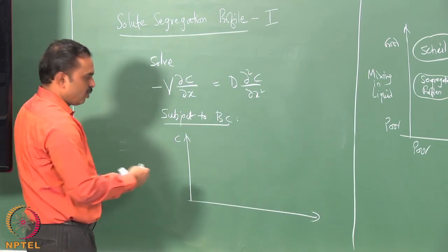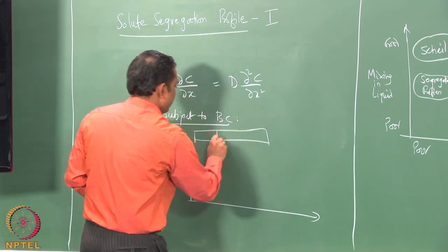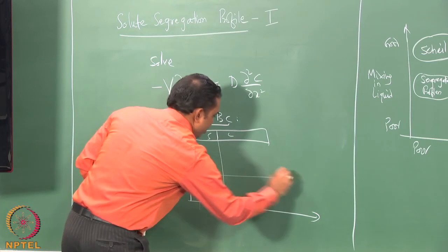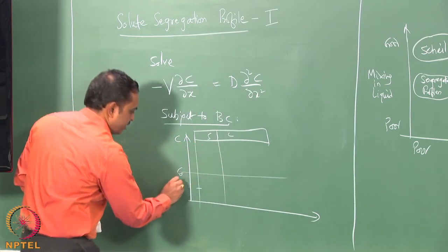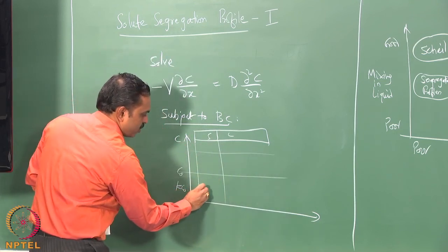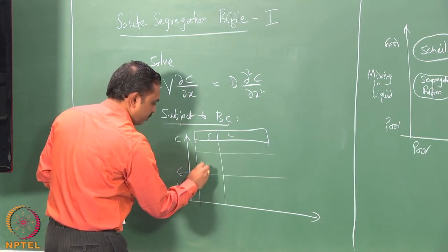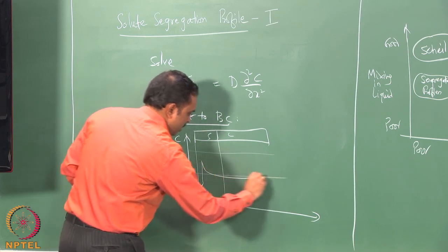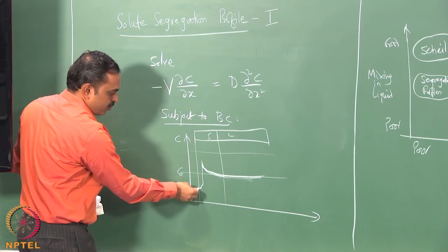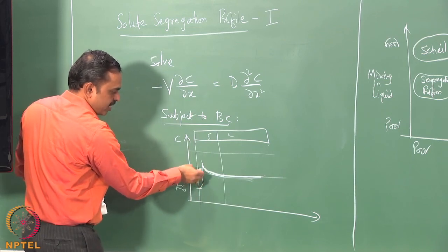If you were to look from a stationary coordinate system at how this profile of composition is going to be from the solid to liquid as it is moving, then you would notice that if C naught was the composition, initially you will have K C naught, and you would see that the composition has to go up like this, because the initial solid to form will be K C naught, the average composition is C naught everywhere, and however much solute is dumped will be in the liquid.